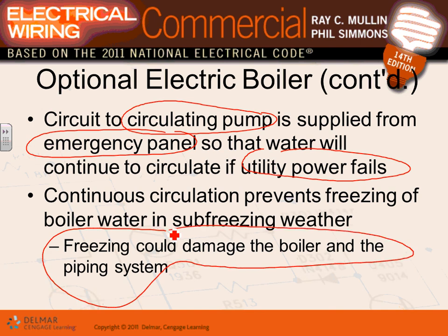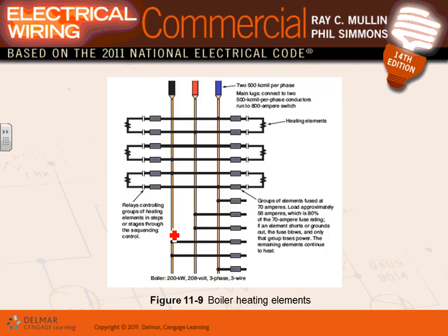You have to have a way. In Minnesota, guys, it's freezing. We lose the power here, right? Now we have a boiler and pipes full of water. What's going to happen to them in two days? It will completely freeze and bust the whole system. So you have to have some means of it. We have a generator right now that circulates certain pumps. You can't run the boiler itself. Well, we have natural gas here, so we don't worry too much about it. You could run the natural gas from the generator, right? But all you need is just a control circuit. But you can't run the pumps though.